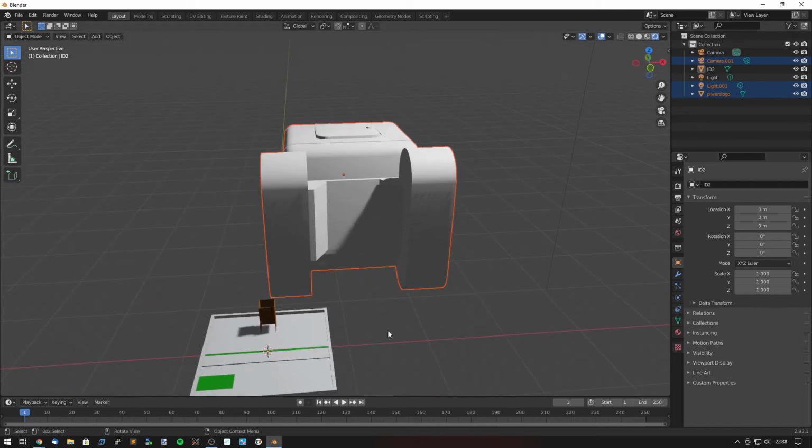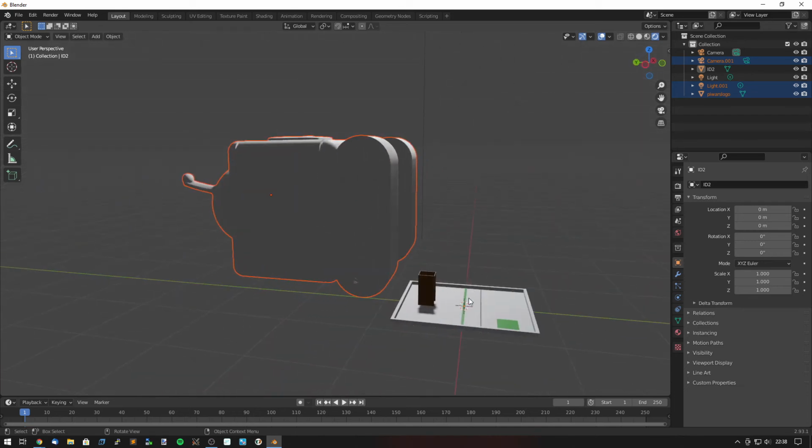So the rotation we have in each of the axes. So if I rotate around here, this is the x-axis, that is the y-axis, and obviously the z is up. Now I want to rotate this around, well, I probably want to rotate it around this line here, so it'll rotate up like that. So that's the x-axis rotation, and I can click on here and click and drag. Actually, you've got to be very careful here. Undo that one. Make sure I'm only selecting that object. There we go. So make sure you actually select the object you're working on. I just hit undo with the Control Z just to make sure I didn't accidentally tilt the entire model that we've got here. So yeah, select the object you want to rotate and just click and rotate this thing.